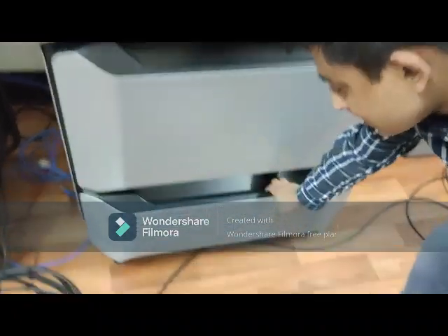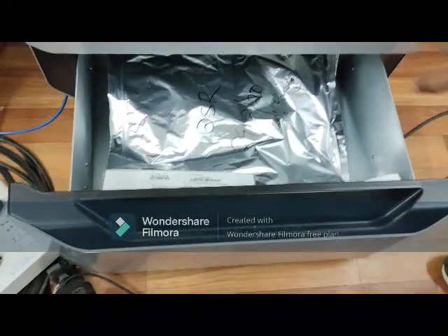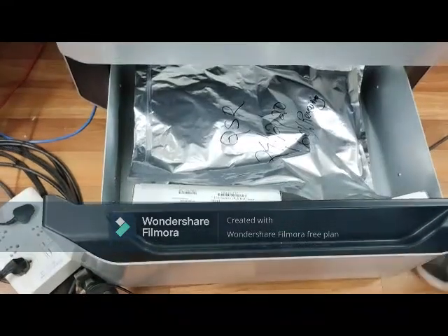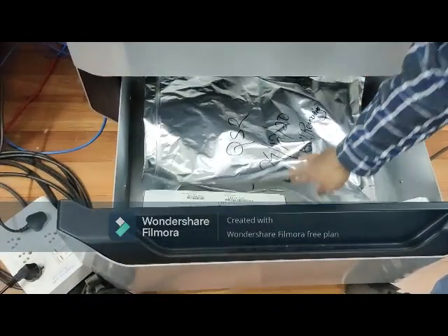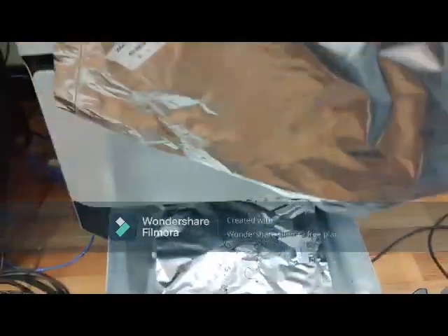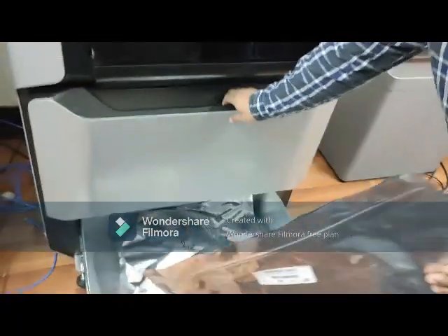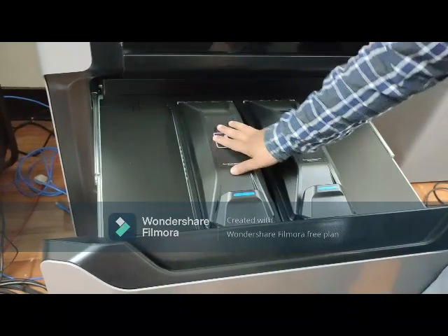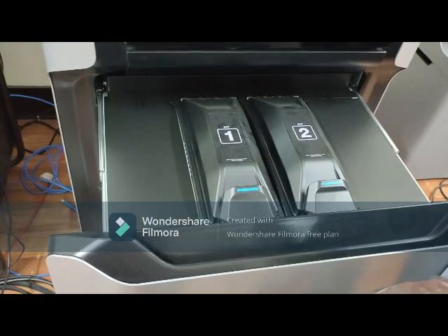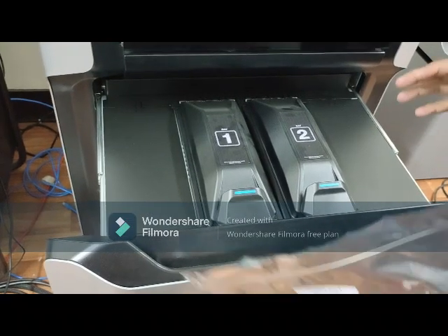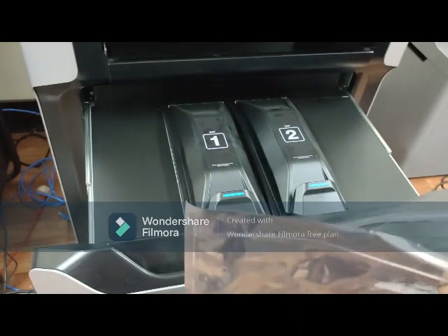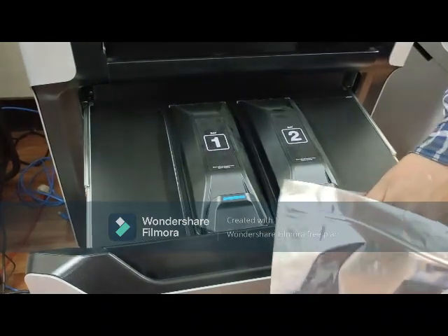Fine, we have some storage section here, so we can keep some things. And we have this kind of plastic, that is the most important thing I think. We are using this kind of plastic to store the filament. Suppose now I'm taking this ASA material out and I want to put ABS here. Taking this out and putting it in some other place won't work, because it will catch some moisture. So to avoid moisture in the filament, we are using this type of plastic bag.